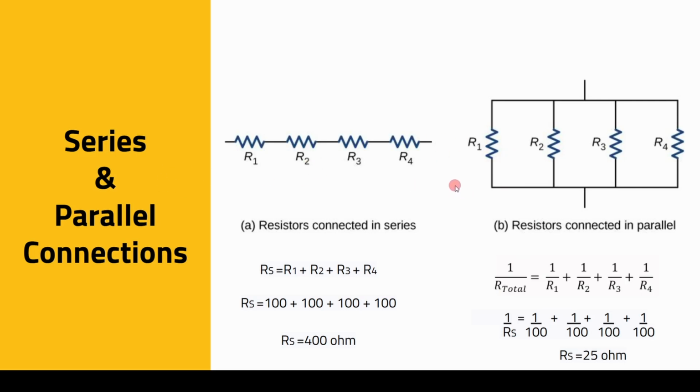So it's useful to know these kinds of relationships, because it helps you when you are trying to answer the question: what resistor do I need to connect to an LED so that it doesn't burn up if I connect it to 9 volts, and I know that the LED requires 2 volts at 10 milliamps. So this kind of question can be answered using something similar to this. It's basically just the application of Ohm's law.